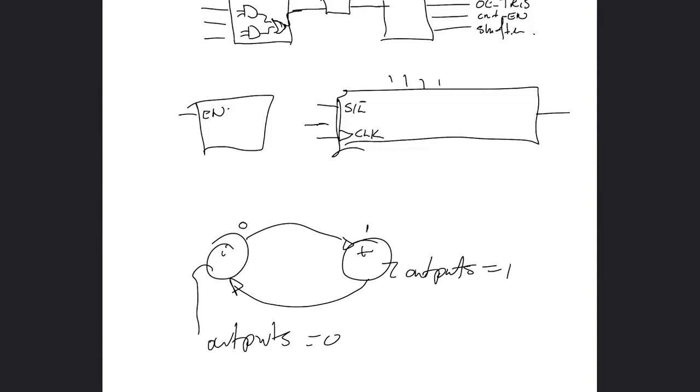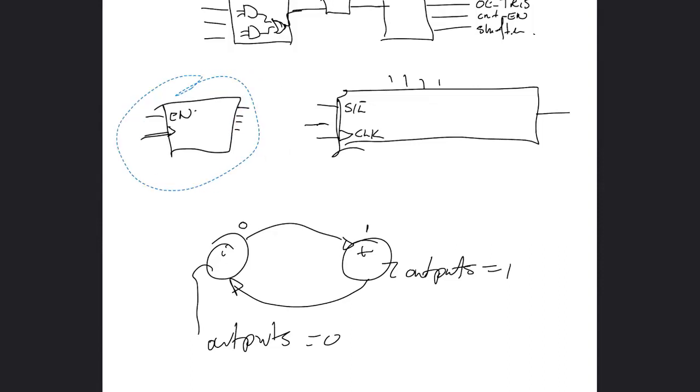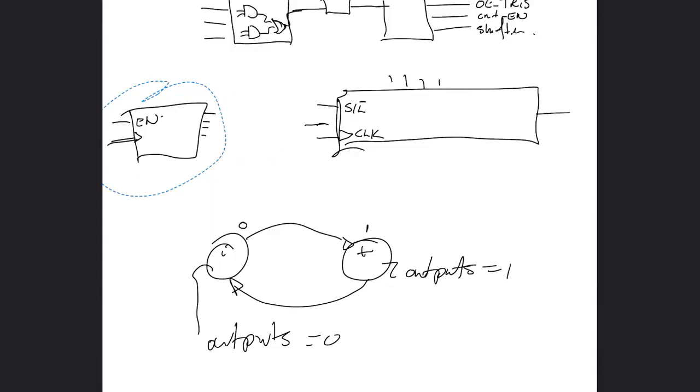It's under memory. There's something called counter, and that counter has an enable. It has a clock input, which obviously means it's going to start counting. It has an output of n bits. You decide n by right-clicking onto it. And those n bits are a binary number. So that binary number is the thing that you have to then check to see if it reached the value that you want it to be.